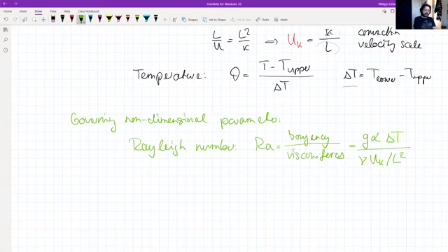So what is now the relevance of the Rayleigh number for this particular case of the Rayleigh-Benard convection? Well, people have studied this flow case for many years, and in fact you can study it yourself in a slightly approximative way at home in the kitchen, in the frying pan when you heat oil, or water in a pan.